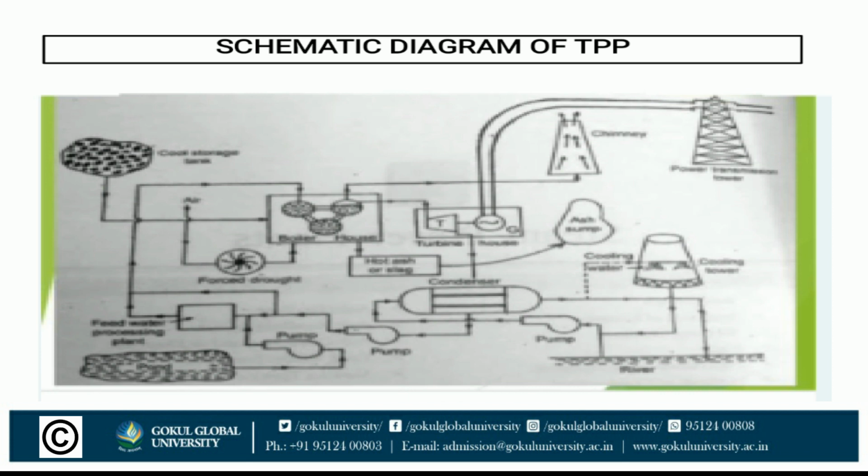Coal from bunkers falls into the hoppers by gravity, and finally the requisite quantity of coal either goes on falling directly on the grate or, where coal spreaders are provided, is spread on the grate up to the rear end with the help of the coal spreaders.